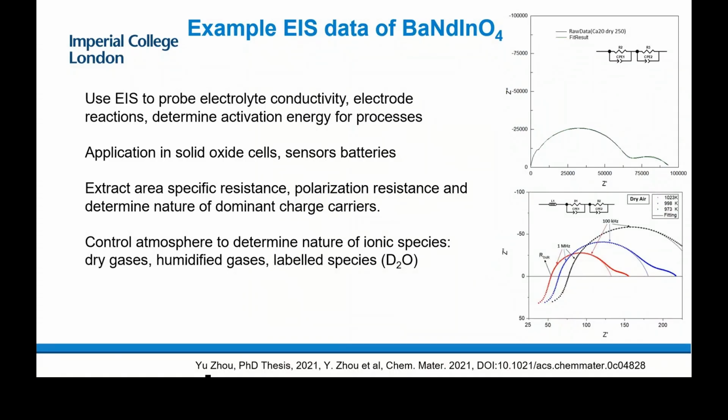So you'll have a total resistance here. You can measure the contact resistance and extract that, so then you're just left with your material ohmic resistance. And that would explain the difference in the starting impedance for each individual temperature, right? Yes, because this is temperature dependent. Okay. Perfect. So the contact resistance obviously won't be, essentially because it's dominated by stuff outside of the hot zone of the furnace, right? So yes, these are essentially going to be materials properties.